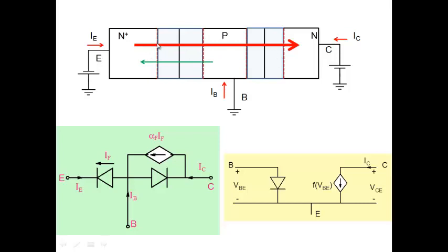This junction simply collects whatever is sent to it. All the electrons that come to it, it just collects. And it's an efficient collector anyway. So whether you apply -1 volt, -2 volt, -5 volt, +1 volt, +2 volt, or whatever, it doesn't really matter. As I change the voltage here, it's not going to change this particular current, and therefore it doesn't change this current here.